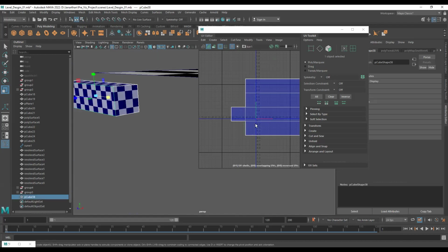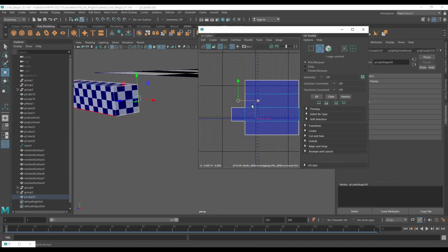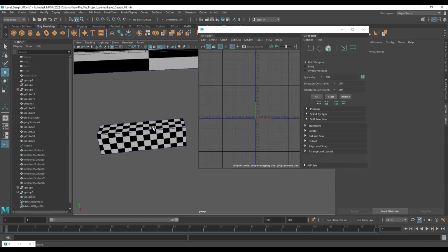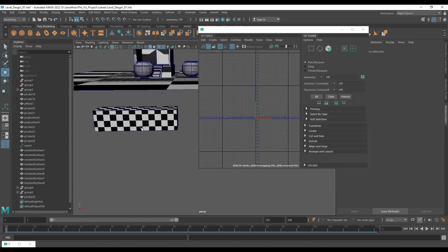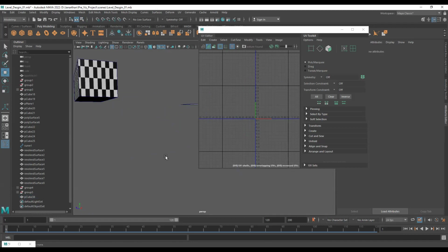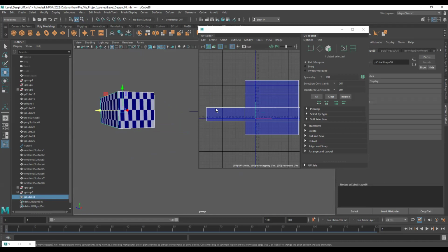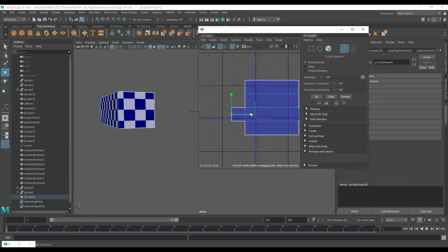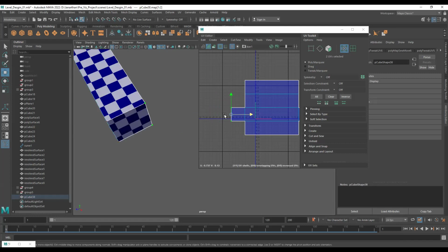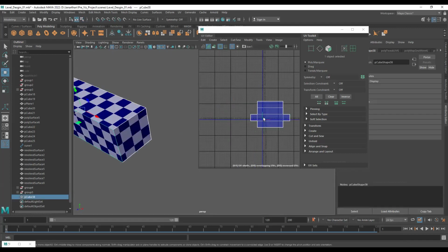In case I select this, particularly this one, I go to the UV and select this UV, move it. Okay. Now you see the top, bottom, left, everything is right. The UV is right, but this side, it is bad. So we have to work on the UV. Right click UV, select the UV and move the UV, make it square. So this is the good UV. Okay, you can identify and analyze by using the checker. Checker is interesting and important thing.